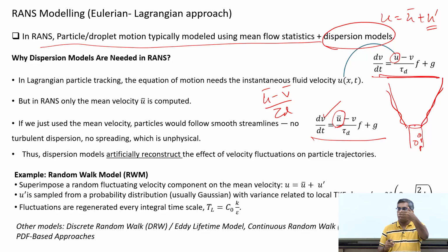That is, you are at a fixed location, and you are time averaging the fluid velocity to get this. But you are dealing with the particle in a Lagrangian reference frame. The particle is moving. You cannot treat it from Eulerian reference frame. So, if a particle is moving in space and you calculate time average, it does not make any sense.